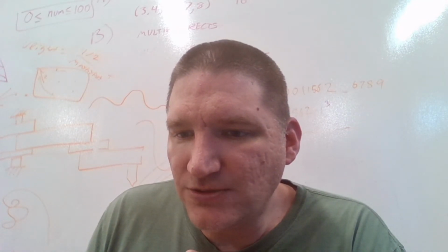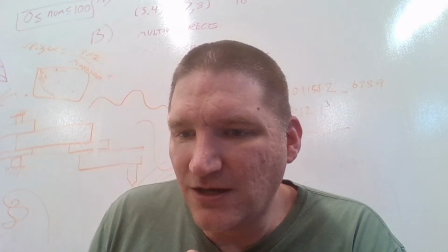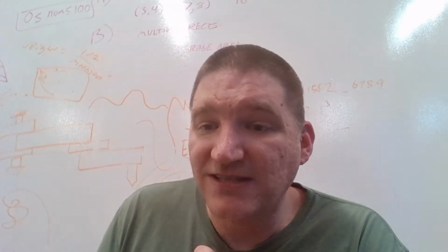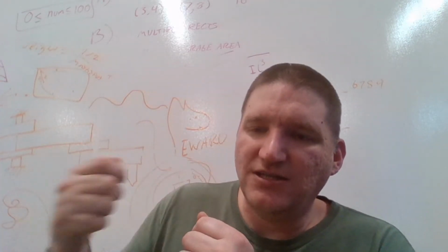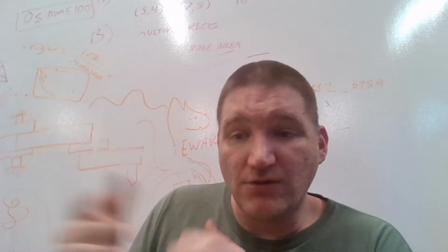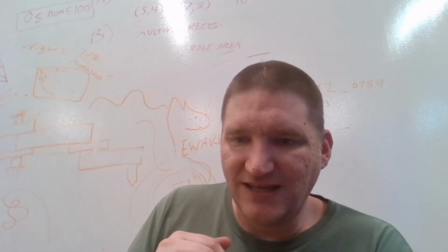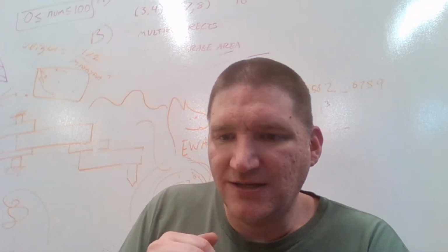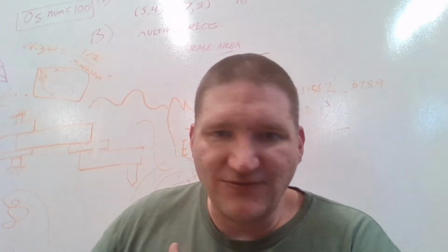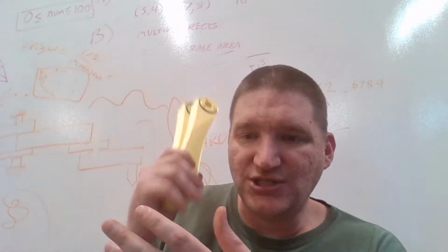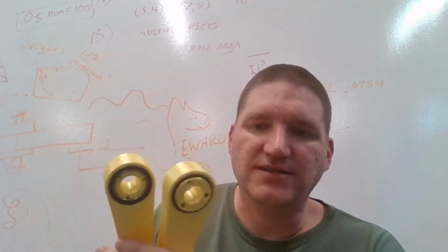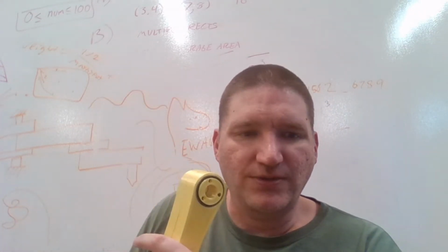If you really need to, you could wrap carbon roving along the outside of the 3D printed arms. Yeah, DJ, I really like that concept of where you print the part and then you can reinforce the outside. If you're going to do carbon fiber, I would say that would be a good way to do it. But again, I want to make it where somebody can just take a part, print it, go use it, and you don't have to do anything fancy.